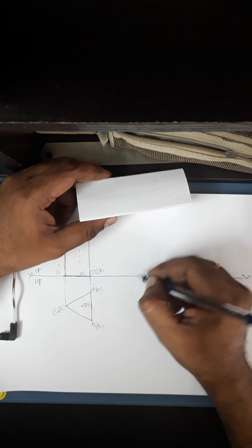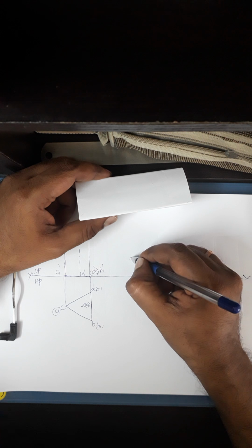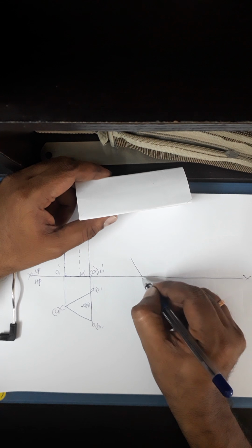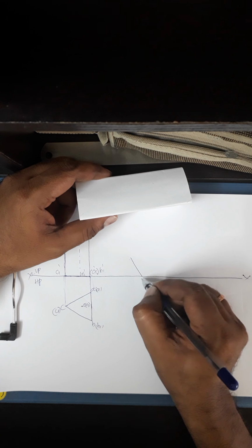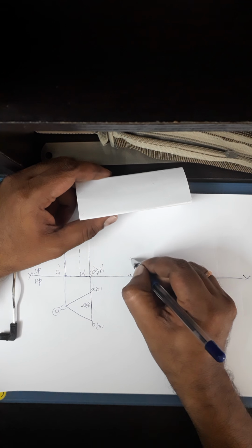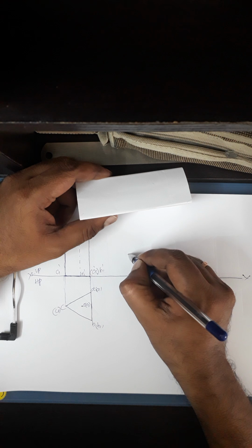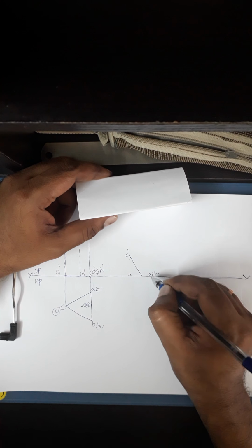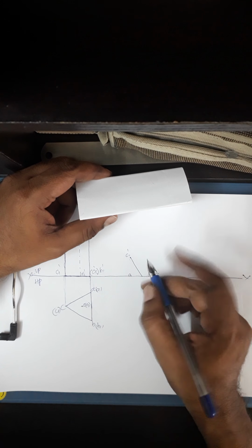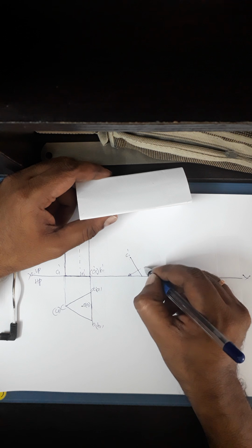So 90 minus the 60 degrees I've taken. I'll take this length and incline this base at 60 degrees. So this is A1 B1. I'll write here A1 B1. I'll take this length and transfer it here to get the point C1 dash. Right? Then I'll locate this axis. I'll just transfer it here. So this is the axis line. If I draw the axis line, okay, see.